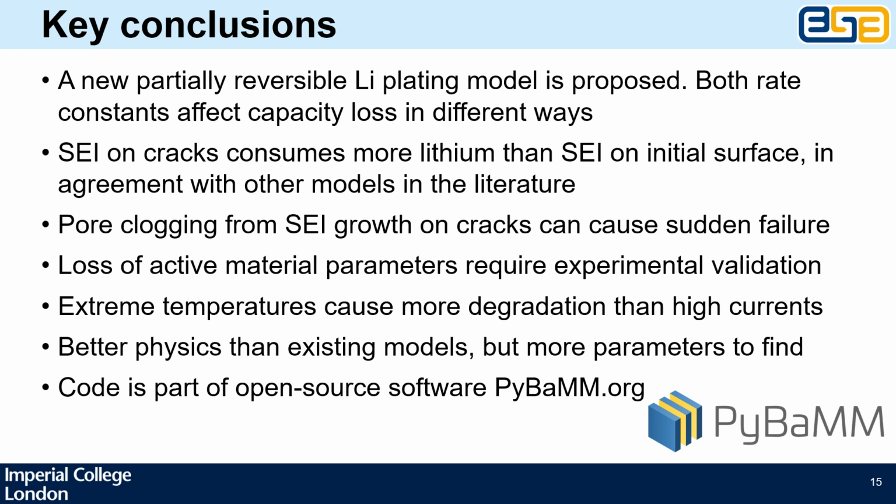Pore clogging from SEI growth on cracks can cause rapid sudden failure. We have a loss of active material model, but there are a lot of unknown parameters, and therefore that model needs more experimental validation. For this parameter set, extreme temperatures cause more degradation than high currents. But then you could argue if we used higher currents, we would get a different outcome.